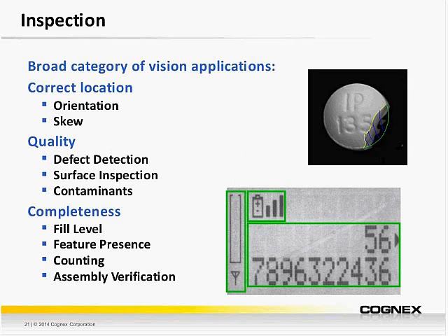Machine vision systems also efficiently perform various types of inspections, verifying quality and assembly to determine whether items meet requirements and rejecting those that don't. For example, presence-absence checking for assembly verification essentially verifies the part components are present and in the correct locations. Defect detection identifies defects and calculates defect characteristics, such as position and size. Machine vision systems ensure quality by detecting defects, contamination, and functional flaws, such as irregularities.